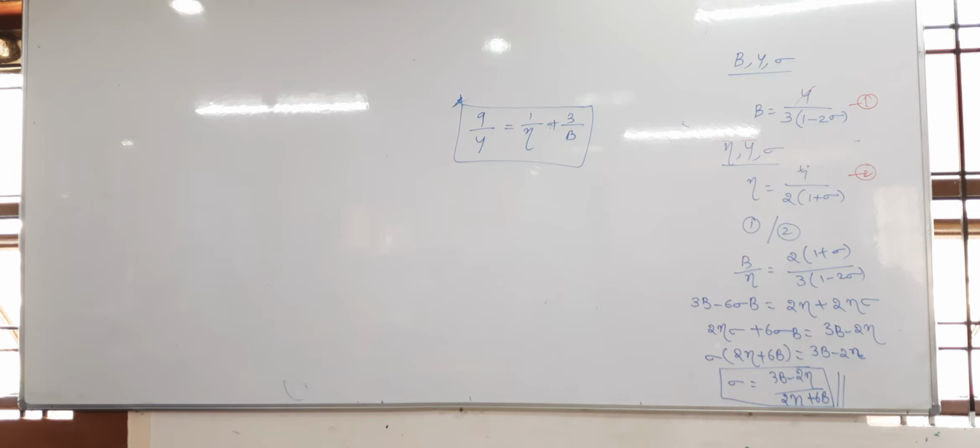A little twisting question only. See, the material's Poisson's ratio they have given, sigma they have given, and also the longitudinal strain given, asking the percentage change in volume. How to do that? What you have to find first of all? Delta V by V you have to do. And wire they have given here. You have to take it as a cylindrical wire and then get the answer. A little twisting, the last line is twisting a little bit.